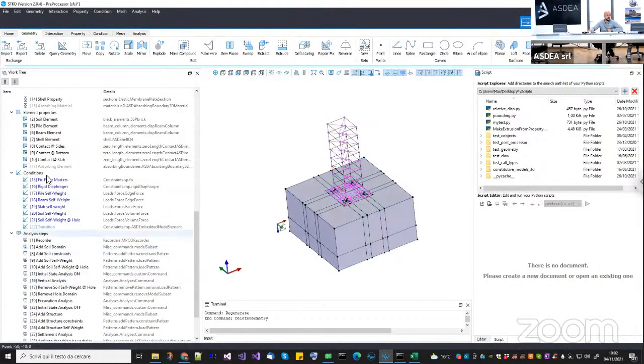As you can see now, here I only have kinematic constraint for the master nodes of the structure, because the master nodes should be fixed in the out of plane direction, the rigid diaphragm, but then you have only forces. And finally, you will need this kind of constraint to attach the coarse mesh to the fine mesh. But this is not mandatory because if you have enough computer power, you can use the same discretization in the entire soil, so you don't need this transition. This is just a way to show you how, if you want, you can create a multi-scale model where you have a detailed model and a coarser model.